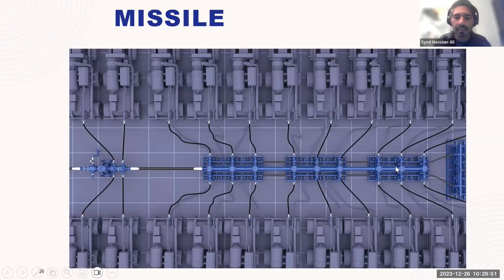This single monobore missile could be all the way up to 7-inch nominal pipe diameter, connected through API 6A flanges. It is just to make sure that all pumps are pumping into a single frac missile, and from here it will be pumped into the wellhead. But before the wellhead, it will go to the manifold first, and then it will go to the wellhead.